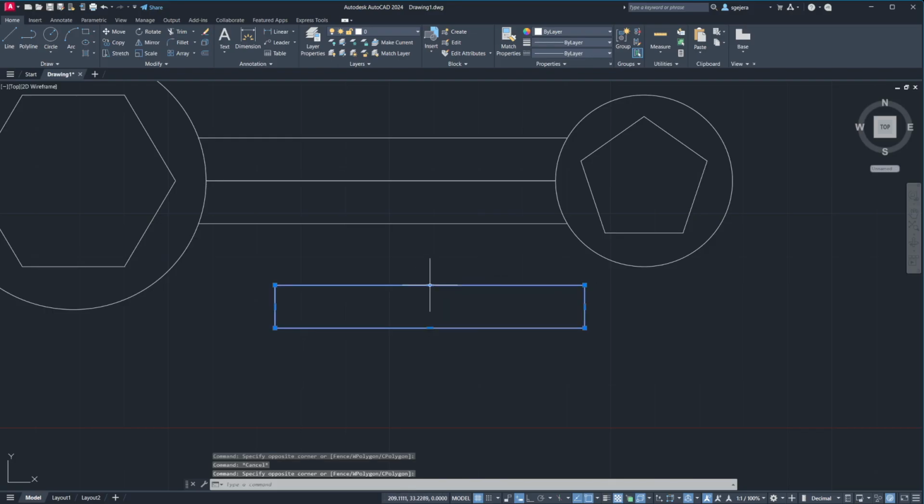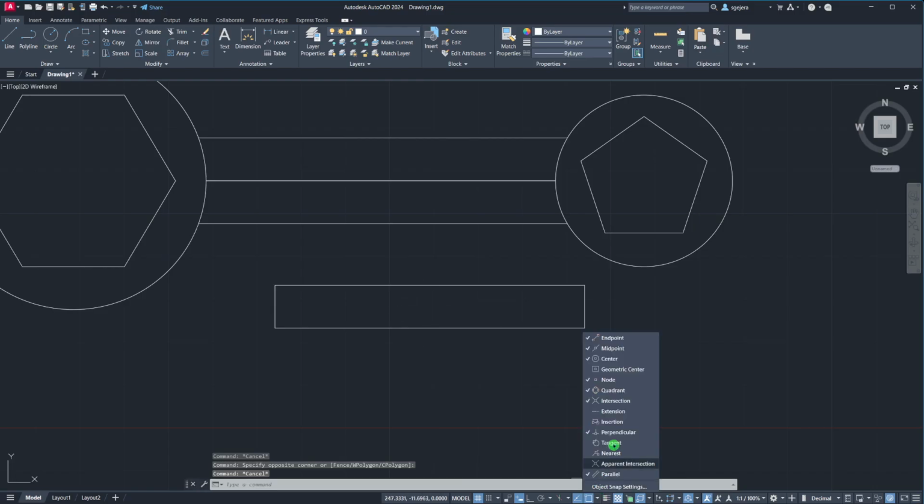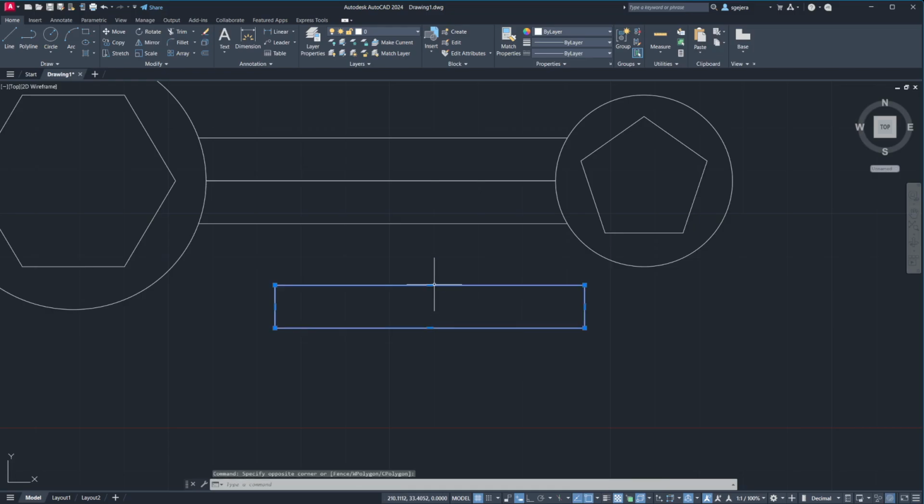Tapos, what I want to do is, I want to access my geometric center, no? Kasi gusto kong i-move to by its geometric center. So, kailangan ko naka-access yung geometric center na na object snapping dito, no? So, I'm enabling geometric center para pwedeng i-move ko to. So, I'll select the object, then press M. M is for move. M. Tapos, hanapin ko yung geometric center niya. I'll just hover over the object. Tapos, lalabas itong point na to. This is the geometric center.